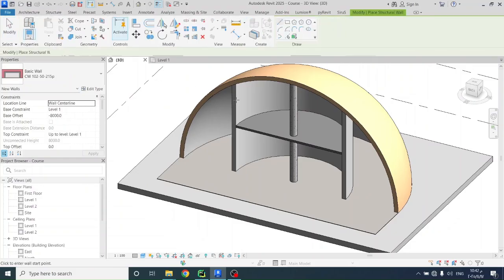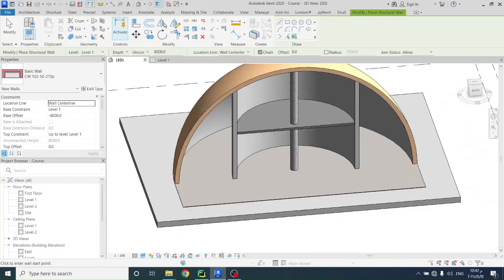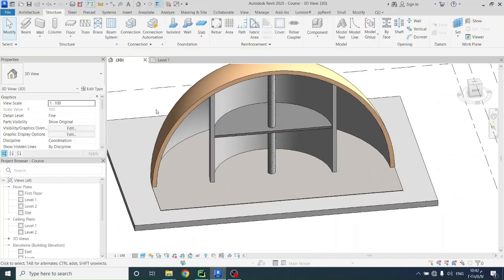So now we have to model the glass facade, for which I used the curtain wall. However, since I already demonstrated how I used the masking tool to model the shell, I'm going to use the edit profile tool to get the profile that I need for the curtain wall. Later on, I'll use the railing tool to model the exterior railing for the terrace and set up the final steps for the project for the documentation step.